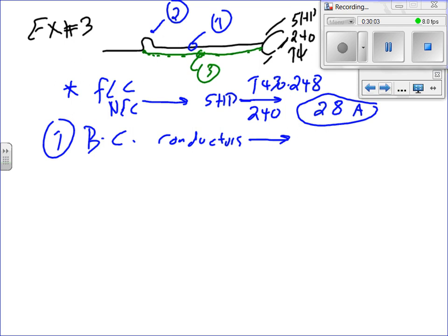Yes, sir. Camille? I answered the question. Which table do you think we are in? It's table 430.248. Is that what it was? 248, and a 5 horsepower motor at 240. Yeah, good point. So my question was that you use 240 volts. Yes. Let me just tell you about the voltages in the table.